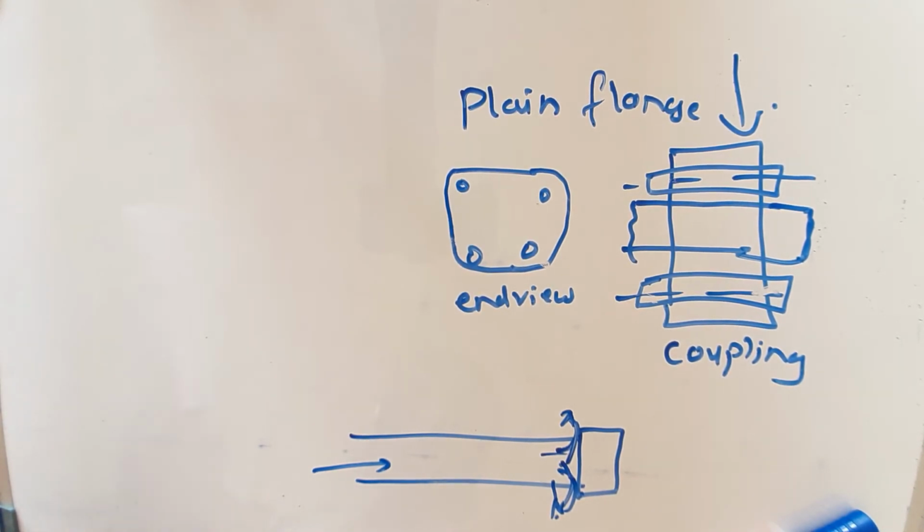While bolting or screwing, it should be ensured that the two pieces are perfectly aligned mechanically. Otherwise, reflection and losses will take place. The end flanges must be smoothly finished to avoid discontinuity at the junction. It is easier to align individual pieces correctly if there is some adjustment, so waveguides with a smaller dimension are sometimes provided with threaded flanges which can be screwed together with ring nuts. Whatever the perfectness of alignment, some discontinuity still exists in the plane flange.